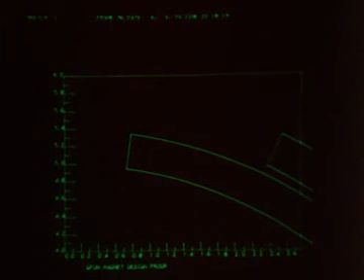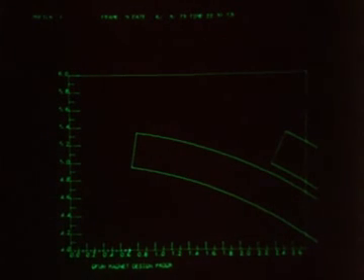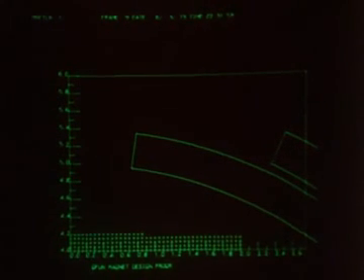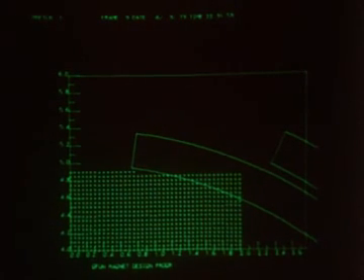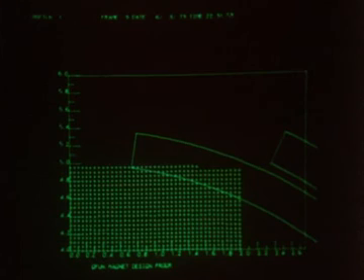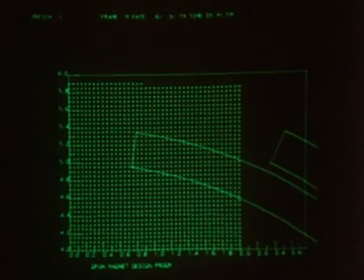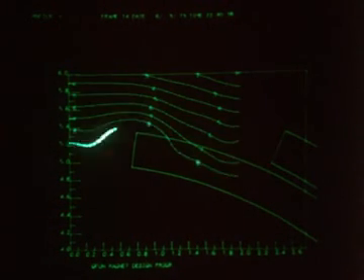He now focuses his attention onto the conductors, first enlarging the picture. He searches for the maximum field by computing the field inside the conductors. The maximum value of the field determines the level of current density at which the superconductor will operate. Finally, contours of the field reveal the highest peak and where it occurs.